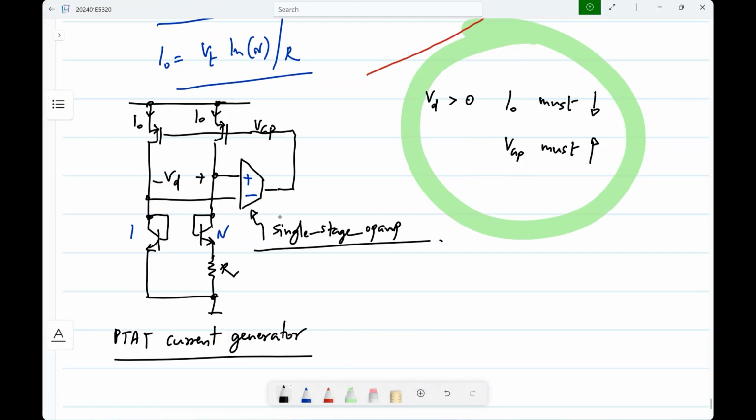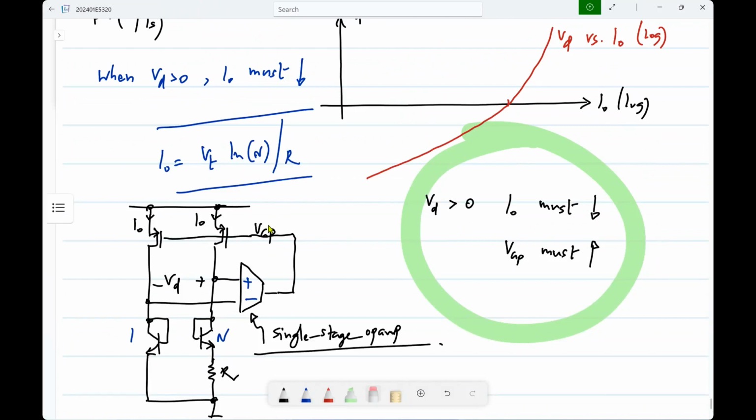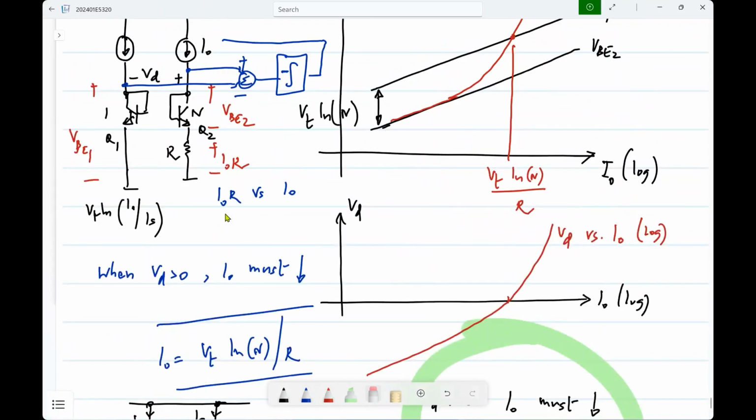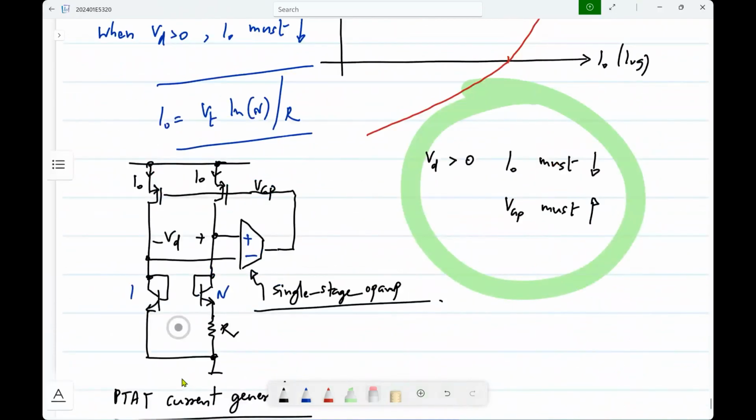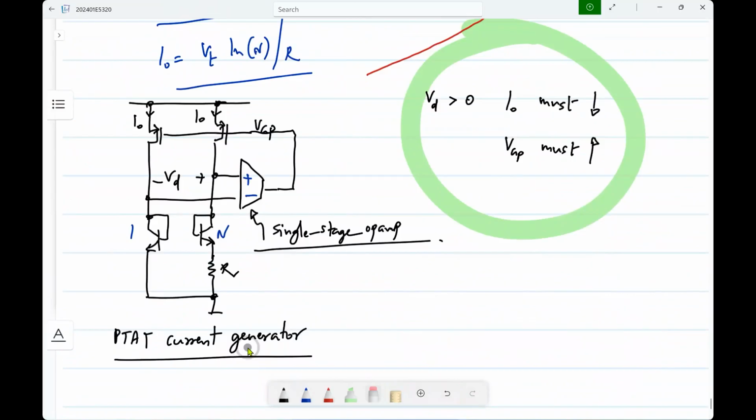Now, I said something about a CMOS process, and I have used bipolar transistors here. Both of these, by the way, this will give you constant GM for MOS, this will give you constant GM for bipolar, but this is the one that gives you proportional to absolute temperature. The other one has some weird temperature dependence. That temperature dependence is good enough to give you constant GM, but this is even more important, in that this gives you proportional to absolute temperature, which is like a thermometer. So this is like an on-chip thermometer. Now, what do we do if we have only a CMOS process?